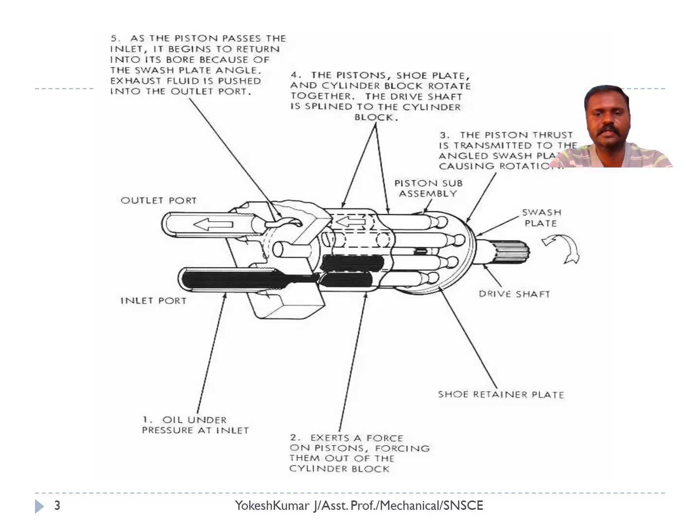And this is the three-dimensional illustration of the motor. The number of pistons can be increased in the radial direction, which increases the power of the motor. Here we have an inlet and outlet port in the stationary cylinder block. Inside the cylinder block, the inlet and outlet ports are connected with the rotating cylinder block. The oil under pressure enters the inlet port and exerts force on the piston. So the piston tends to move outward, or it reciprocates inside the movable cylinder block.